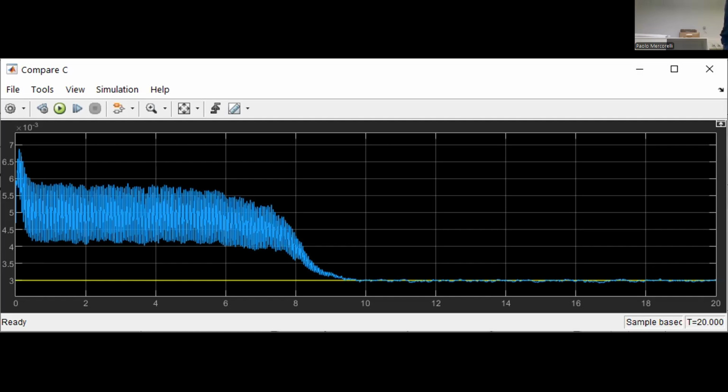I can improve this. I told you also in the case of the motor, putting the initial value of the P matrix not 0, because now the initial value is 0. Do you remember? If you put the initial value of the P matrix, the a posteriori error covariance, as 0, the Kalman filter understands that we are at the goal. This means we can see that it's lazy here. We need 10 seconds, because we inform the Kalman filter with the wrong information. We say, you don't have to do anything, because we have error 0. We are at the goal. Then the Kalman filter is so clever in understanding that we try.